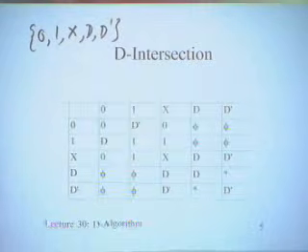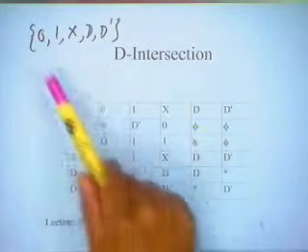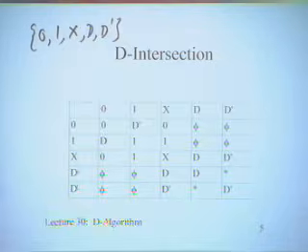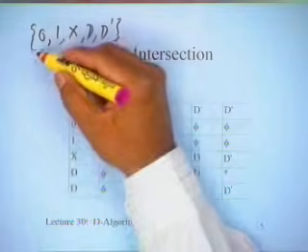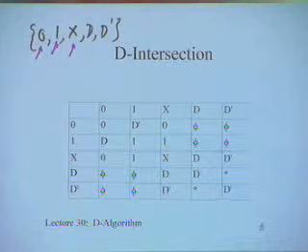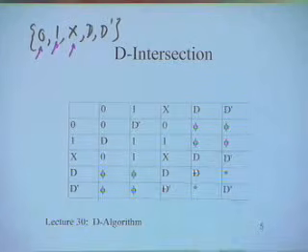We consider that each circuit node can take one of these 5 values. Typically we say 0 or 1, so you extend it to 0, 1, x, D, D bar. What is the meaning of it? 0 and 1, of course. X is: till now I have not assigned any value to it, I do not care till now. Of course, it does not mean that finally these x's will not get converted, but if I do not care what value that node has, then it is x.